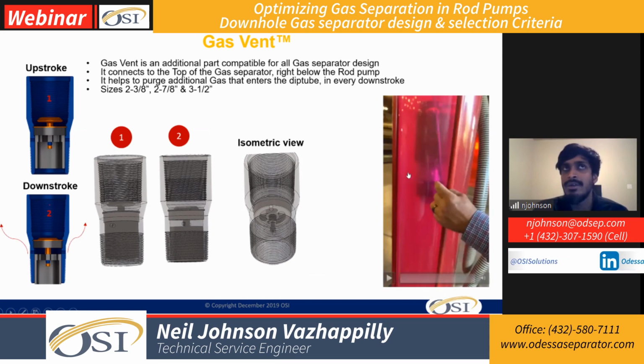One of the things that I wanted you all to visualize is that gas, being lighter inside of the dip tube, if it escapes out or it's already in a free gas section, whatever it is, kind of accumulates in the top section of the dip tube. So that is the reason every time this opens up, we can purge a percentage of that gas out. So the overall pump fillage can be much higher compared to a system where we do not use this gas vent. So this is the video we'll see.